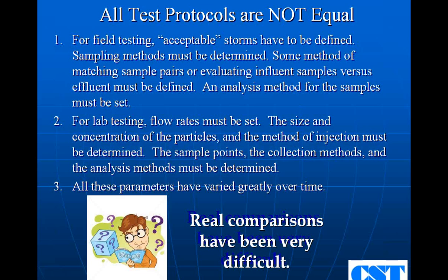Well, test protocols are not equal either. On field testing, they have to have an acceptable storm. Usually they want 15. Sometimes they want 0.15 inches within 25 hours, sometimes 2/10 of an inch within 24 hours. Some people want to limit heavy storms because they feel it gives an advantage to proprietary devices, for example. And they only want small storms because they believe only the small storms are important.